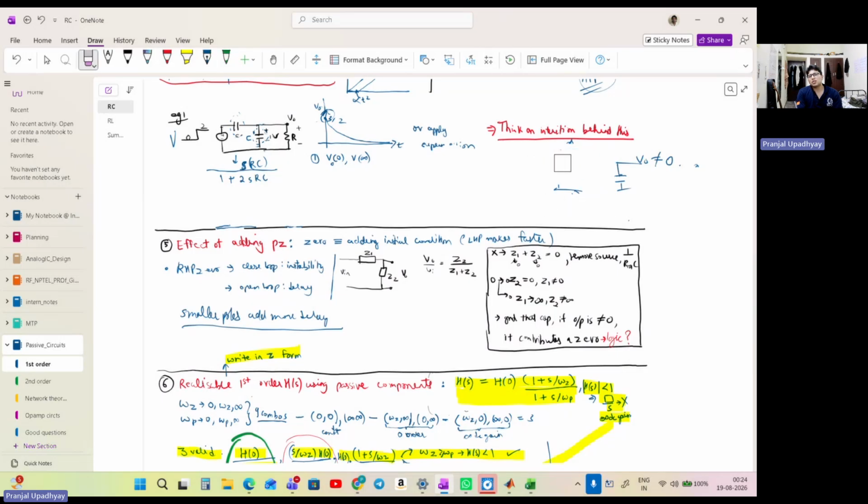Now, what is the logic behind this? When does a cap fundamentally get shorted? A cap gets shorted at a high enough frequency relative to it. For example, a capacitor has some value and its impedance is this. So at a certain high omega, this overall impedance will be low, and thus we can short it at that particular moment. So in this approach, where we have some circuit and we are shorting every capacitor one by one, what we are effectively doing is sweeping frequency from 0 to infinity and checking which capacitors are getting shorted and how the output is getting affected.